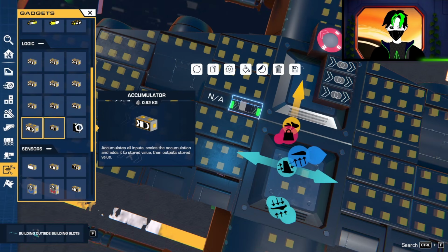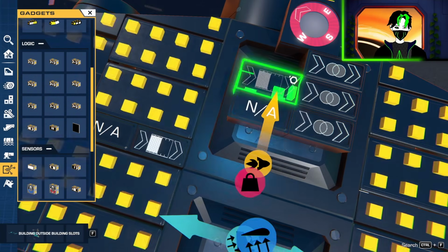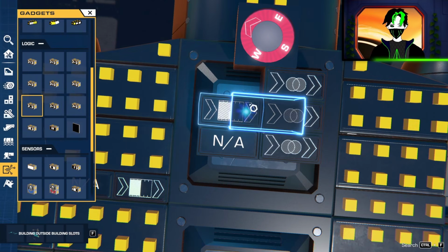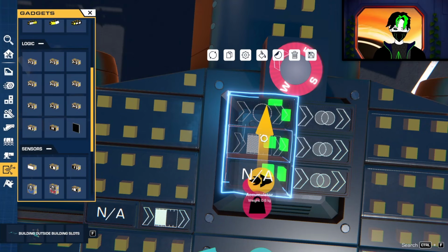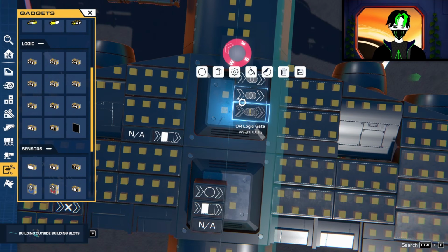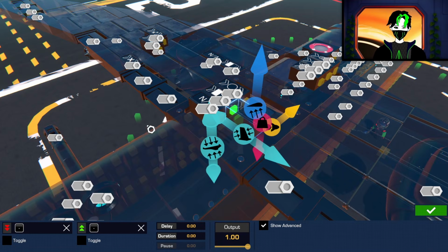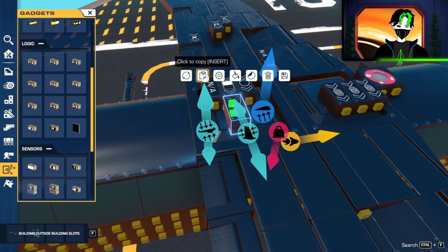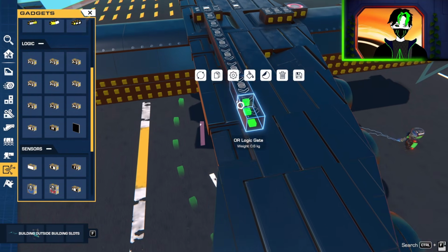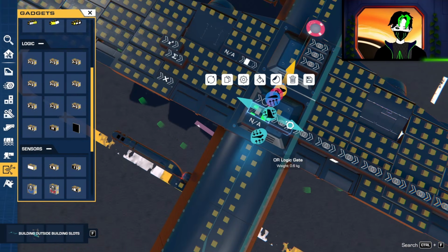Accumulator. There. Accumulator. Number display. Accumulator will have a NOR gate. Perfect. This is just me measuring how much time delay each logic gate has. Except we can put like 10 of them so that we're more accurate. A NOR gate is going to send the input into that. That's one. One jump. 2 jumps. 3, 4, 5, 6, 7, 8, 9. And 10th jump is into the accumulator.